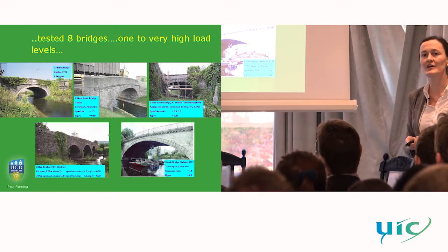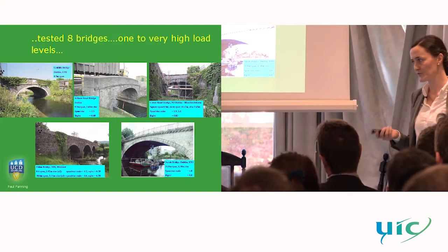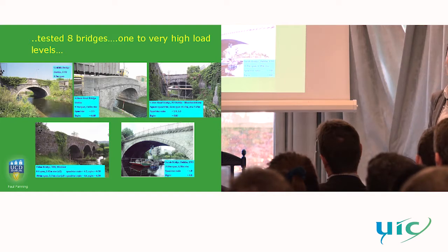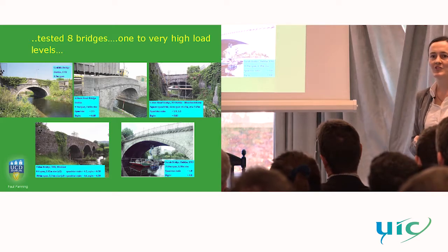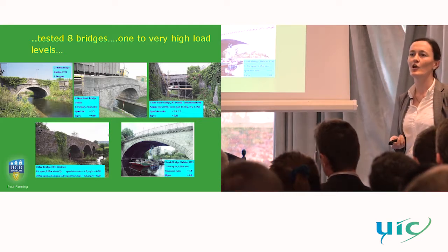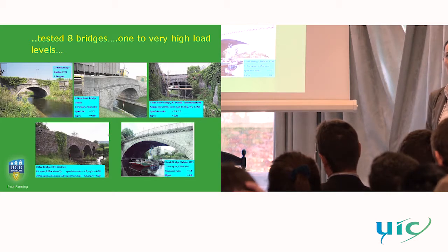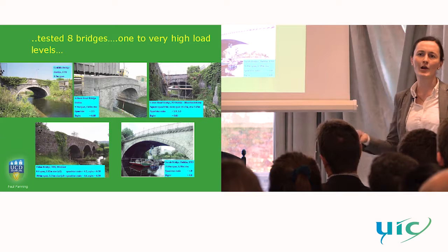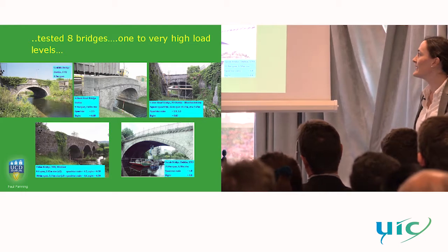As other people have alluded to, there's pre-existing test data carried out at the Building Research Establishment and the Transport and Road Research Laboratory, and for other research projects. Much of that test data is very strongly focused on recreating two-dimensional conditions in some capacity or other. Sometimes that's looking directly at a unit width arch with all of the other elements stripped out, or sometimes it's looking at a three-dimensional structure, but then applying a line load across the structure, thereby recreating what you consider two-dimensional loading conditions.